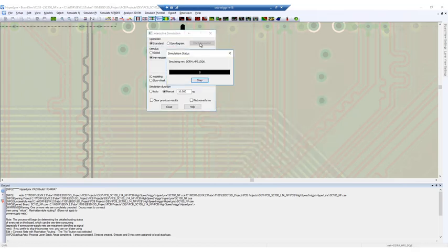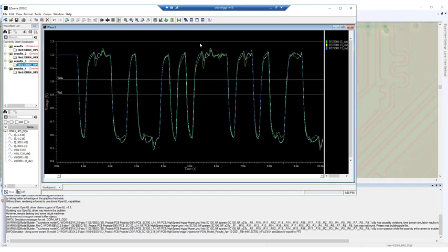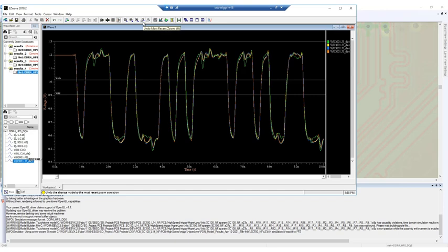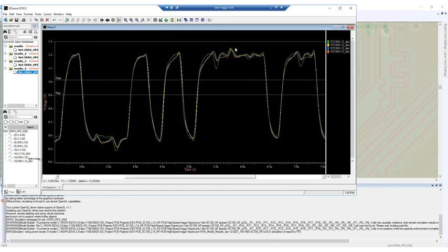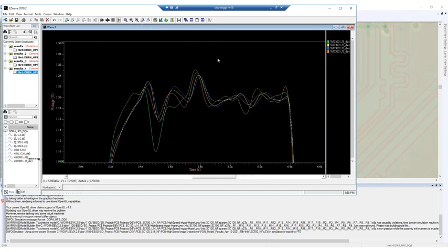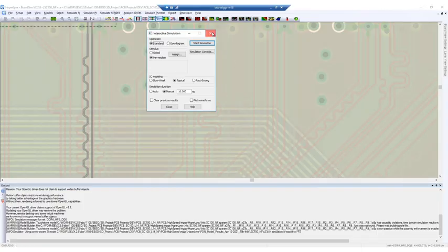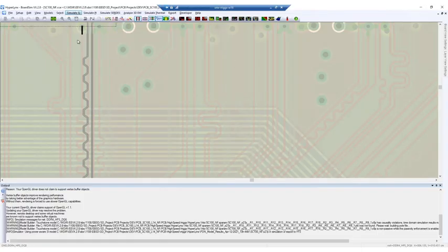We are modeling all of this behavior with an S parameter, and this includes the area fill coupling, the trace-to-trace coupling, via coupling, return path issues, cavity coupling, etc. With this S parameter, we introduce much more effects with the power-aware to the PDN than we did before, and therefore we can get a more accurate simulation of what the board will behave like in the real world once it's fabricated. This doesn't look too bad, so we can move on to the DDRX wizard for the advanced analysis and final report.